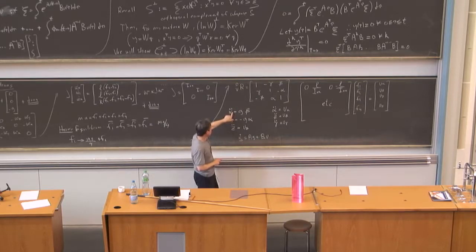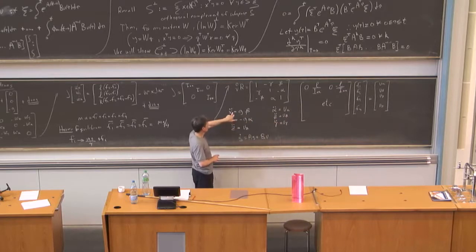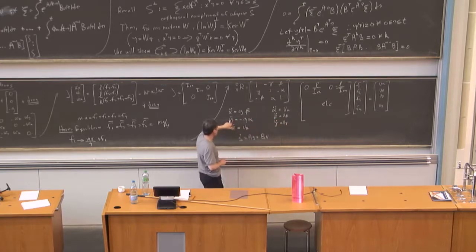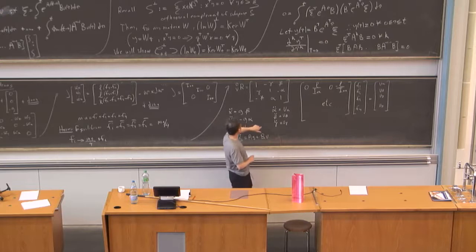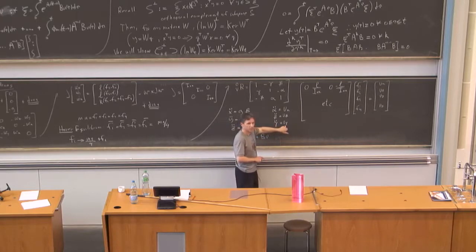Basically, the second derivative of x is equal to g times beta, but the second derivative of beta is equal to u beta. So one way to think about this is that the fourth derivative of x can be affected by control input u beta. The fourth derivative of y can be controlled via u alpha. Z double dot is controlled via u z, and gamma double dot is controlled via u gamma.